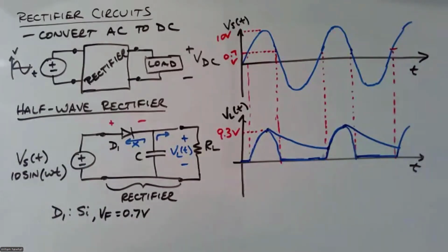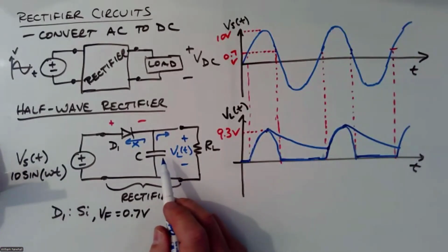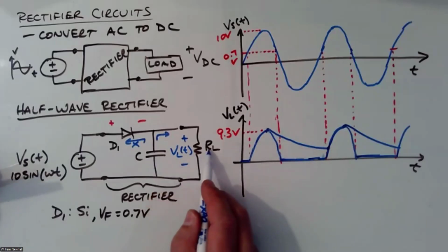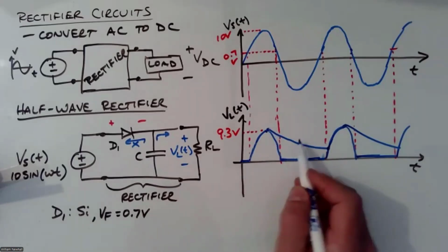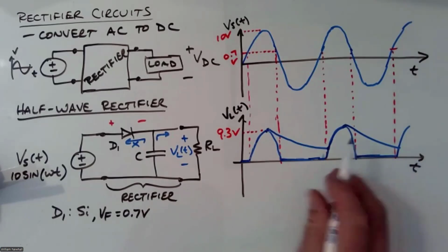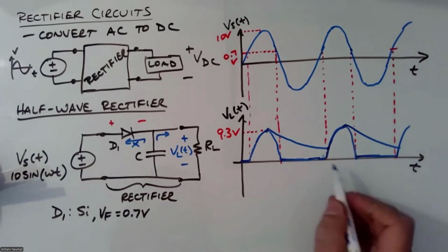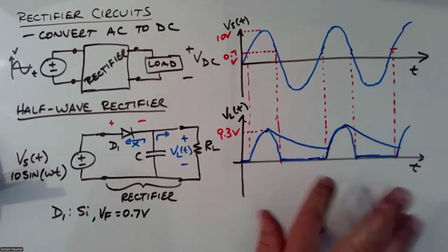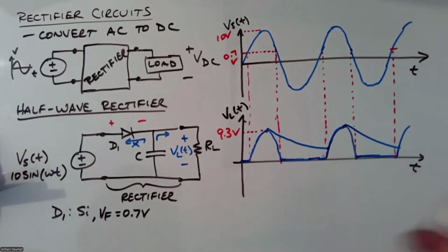But what we can do is take this capacitor and make it big, right? So the time constant of this R_L and this C for this shape here might be, I don't know, 5 tau might be out here somewhere. But what if you take that C and you make it bigger? You're essentially going to move 5 tau way off the whiteboard here.